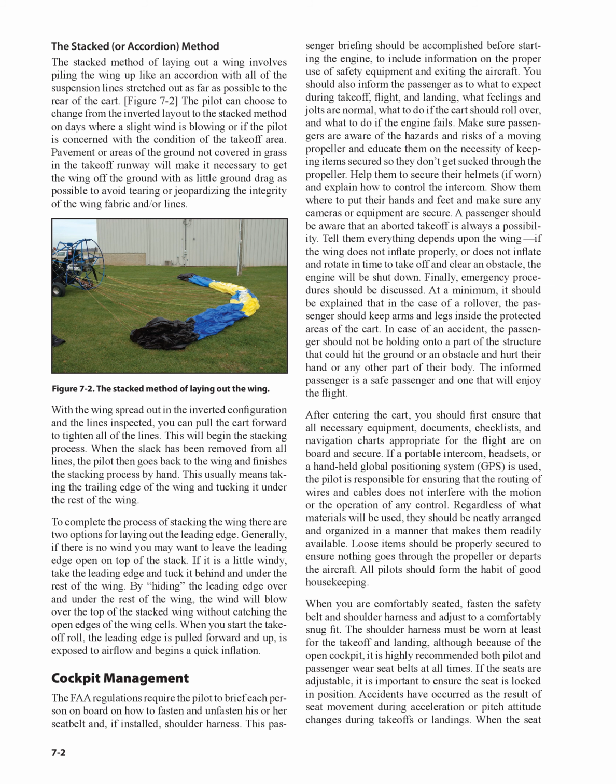The FAA regulations require the pilot to brief each person on board on how to fasten and unfasten his or her seatbelt and, if installed, shoulder harness. This passenger briefing should be accomplished before starting the engine, to include information on the proper use of safety equipment and exiting the aircraft. You should also inform the passenger as to what to expect during takeoff, flight, and landing,